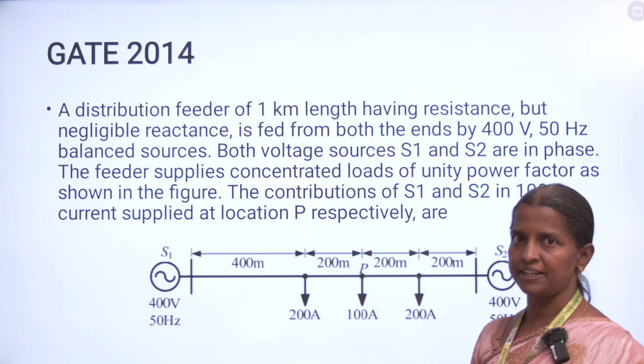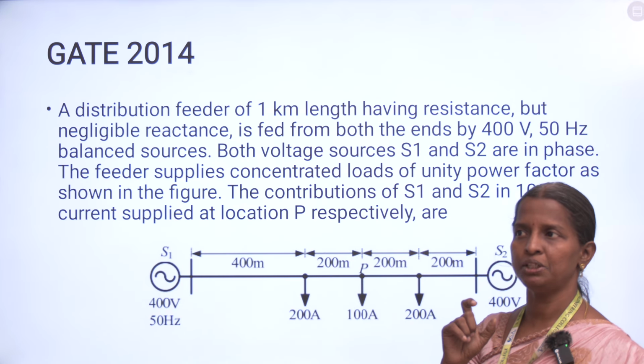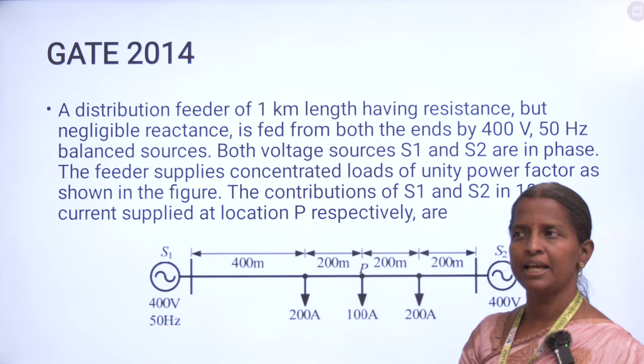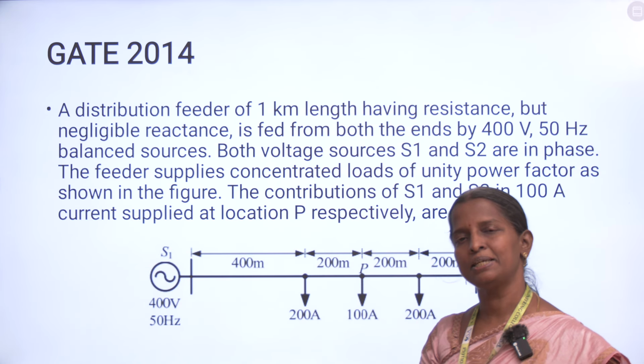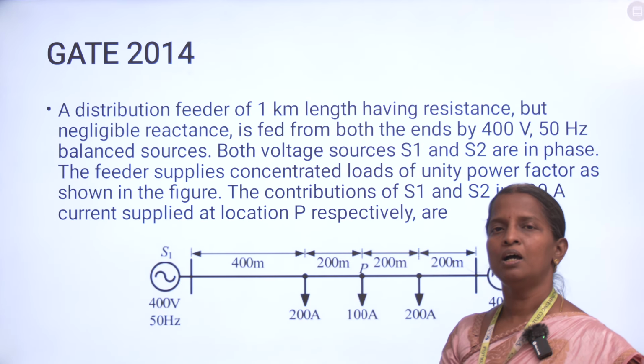If it is out of phase, you have to calculate the phase angle. That is, the angle between the voltage and current is called the phase angle. Why we are calculating the angle between voltage and current is because it is important for the power factor. Power factor plays a major role in AC circuits.